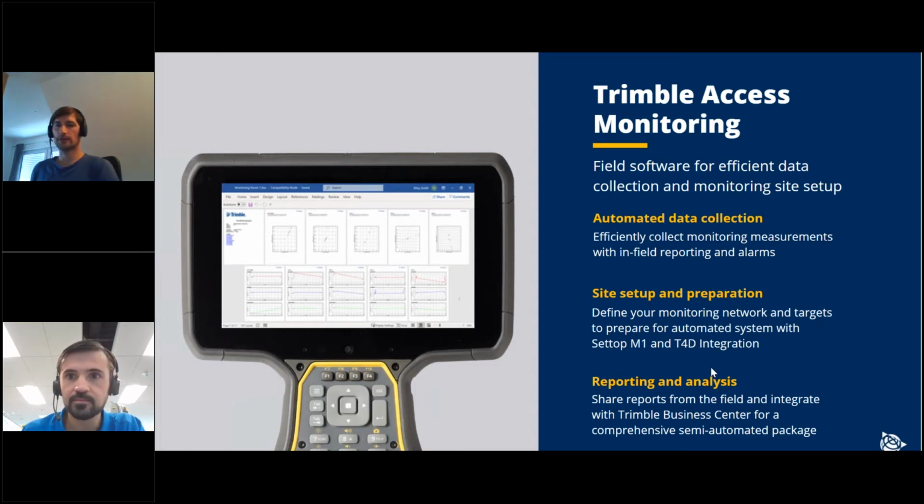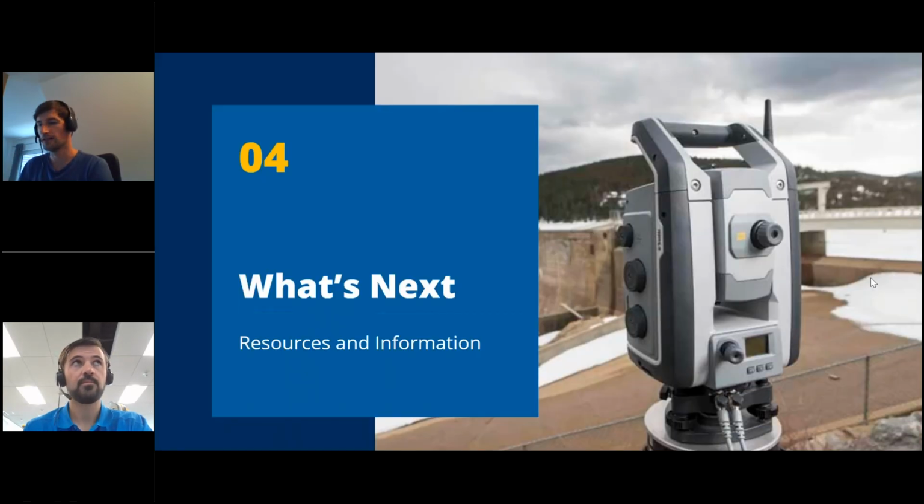Yeah, you can do the initial site setup and preparation using Trimble Access Monitoring. And as Riley just explained, you can then transfer it to the Setup in One, and through the Setup in One, it is then also transferred to T4D. So that's one option. But you can also directly import a site setup into T4D. On top of that, you can also import round measurements and process them in T4D, or add this information to your permanently installed monitoring devices. So that's all possible. Yes, there is a nice integration between Trimble Access Monitoring and T4D.